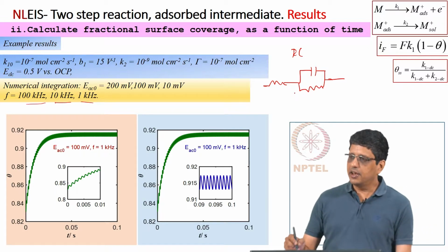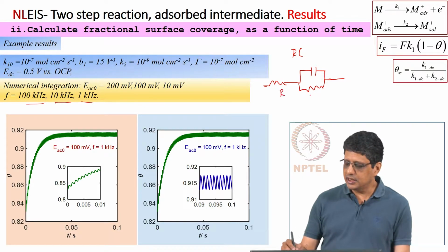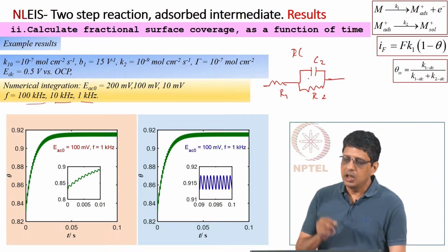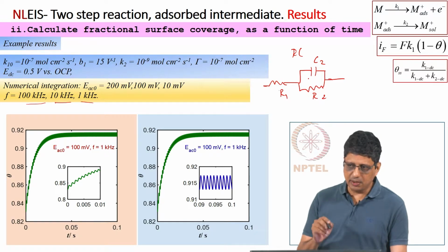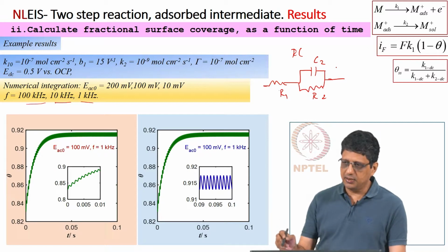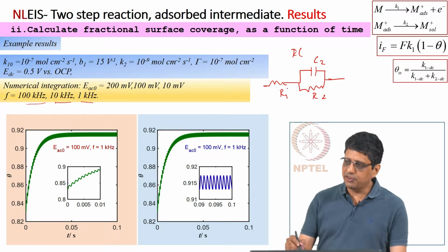if I just take the Fourier domain and calculate the resistance here, use the resistance here, and use the capacitance here, I can find the impedance. But if I supply a sinusoidal potential, it will take some time before it gives me the steady periodic result, and if I take the steady periodic result and use Fourier transform, I will get the same expression for impedance.